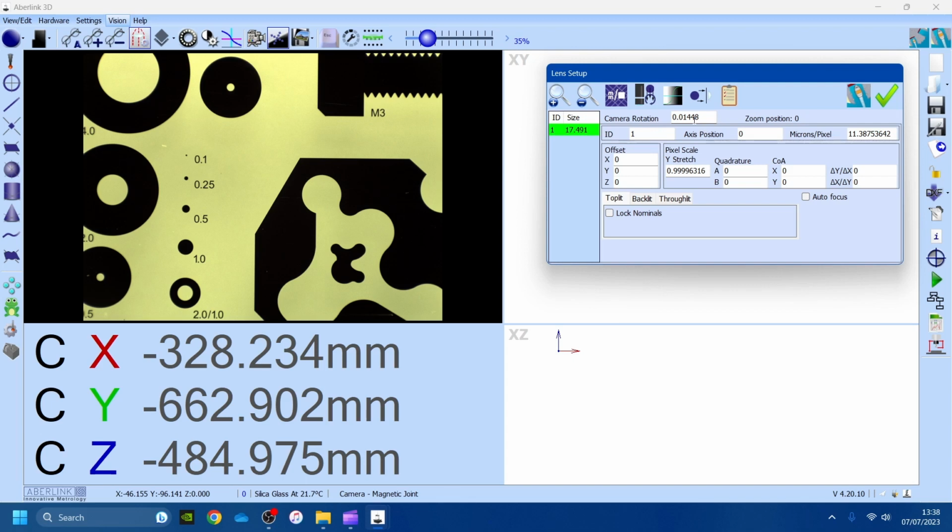and we now have fully calibrated the camera. However, I would recommend running some calibration tests, which is part of the next exercise, just to verify that the camera is actually indeed measuring correctly and the Z rotation isn't causing any problems. This will be really important on bigger components where the camera has to move around quite a bit to measure them.